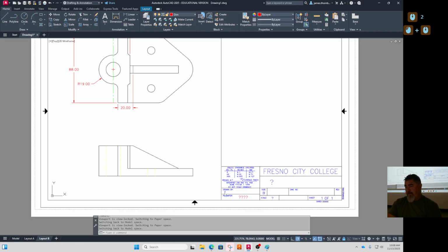And then go in and edit, double click out here, get back to paper space. You can also see over here the icon. It's like this big triangle. That's our paper space icon that we're drawing on the paper. For in the viewport, we get the model space UCS, just like in model space. Also down here, it says model. I click on that, it says paper, and it kicks us back out to the paper space. Now I'm drawing on the paper there.